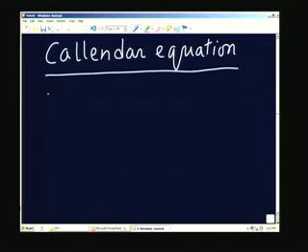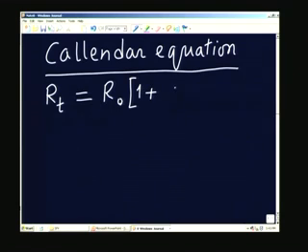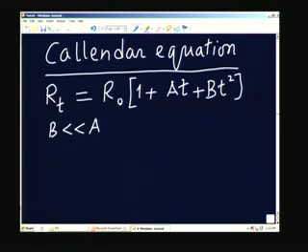So, I said that the resistance of the thermometer, I will say RT, is the resistance of the platinum resistance thermometer at any temperature T, can be written as R naught into 1 plus A times T plus a small nonlinear term, I will say it is equal to Bt square, where B is very small compared to A. This is because of slight nonlinearity.